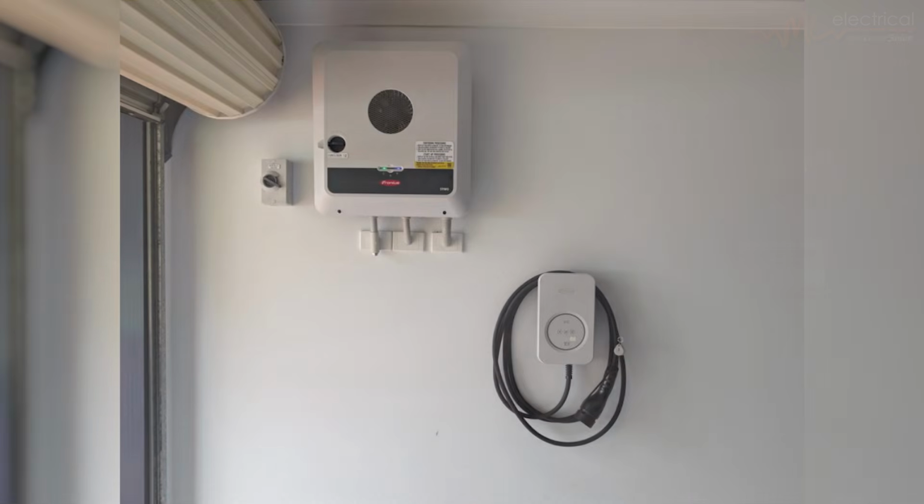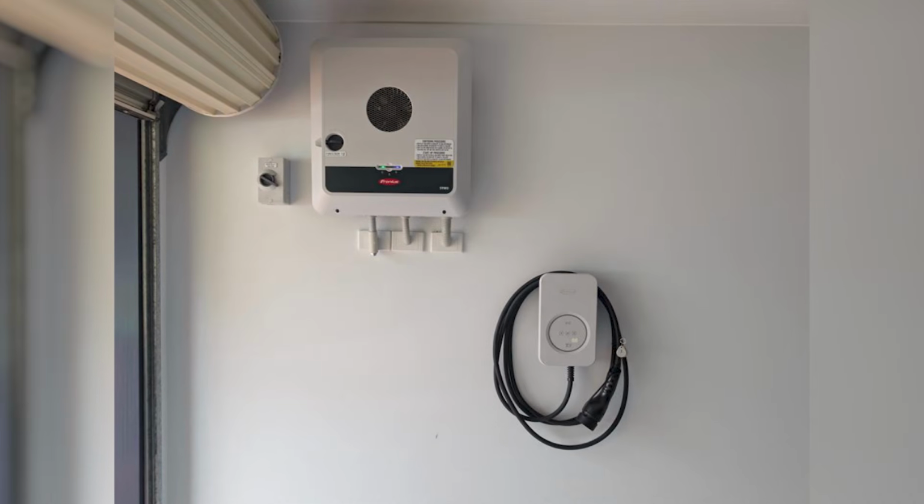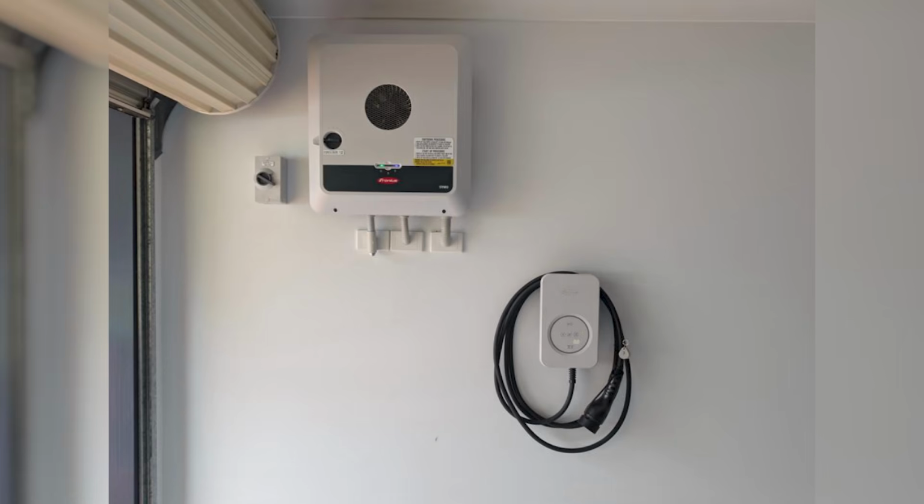So the first thing we want to do is put the inverter in a cool location, like a south-facing wall or in the garage. We definitely want to keep it off the northern side or the western side where it's going to get cooked in the midday sun. But the other thing we want to do is keep the inverter close to the switchboard if it's possible to do so. This does reduce the cabling costs, and so it's partly a cost thing.